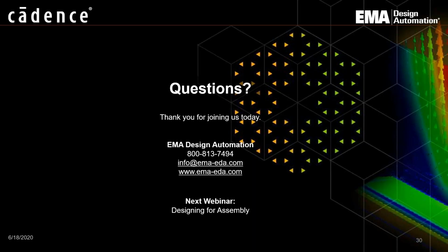And let's see, our first question, CT, is, does the user need to create the CFD model for the thermal simulations, or does Celsius already come with some power maps and information for the ET co-simulation? The power map on the chips comes from user supply. You can use IC design tools to produce the power map.